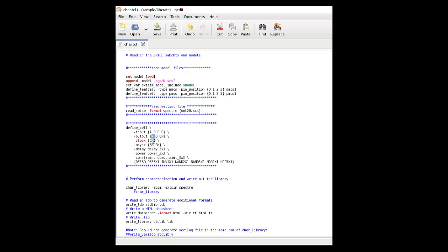The next comes the clock, which is with respect to the sequential block, and the asynchronous signals are defined using the switch async. Then the next three statements are the templates that we have defined earlier being applied to the cells that I have defined at the bottom. This includes the D flip-flop with set and reset, the D flip-flop without set and reset, the inverter, NAND and NOR.